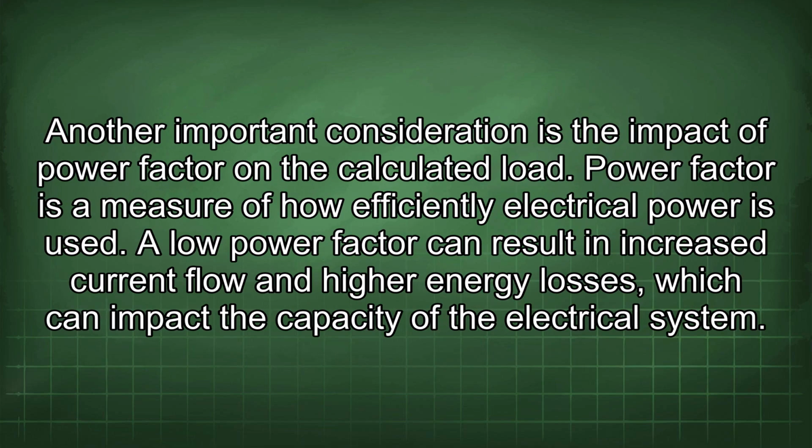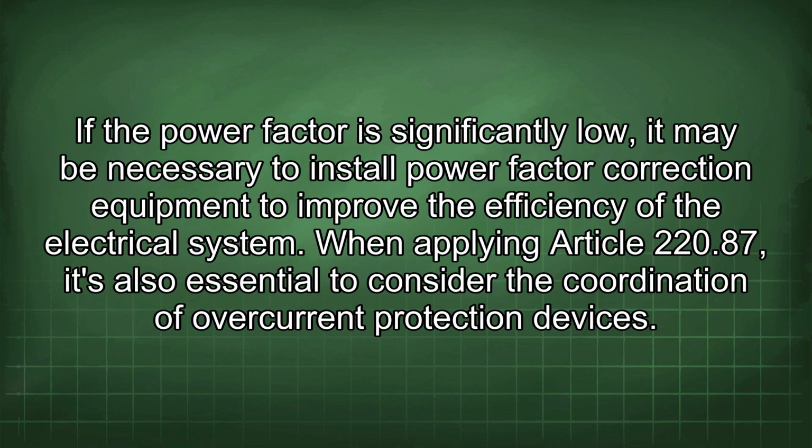Another important consideration is the impact of power factor on the calculated load. Power factor is a measure of how efficiently electrical power is used. A low power factor can result in increased current flow and higher energy losses, which can impact the capacity of the electrical system. If the power factor is significantly low, it may be necessary to install power factor correction equipment to improve the efficiency of the electrical system.